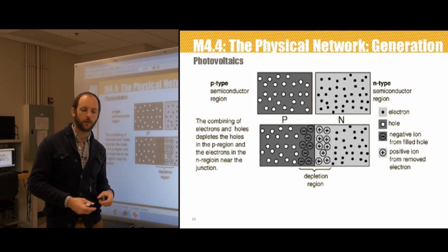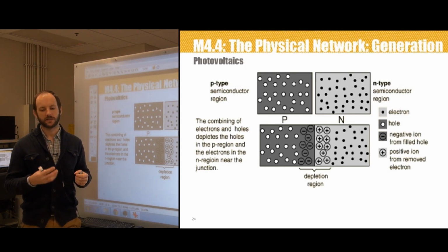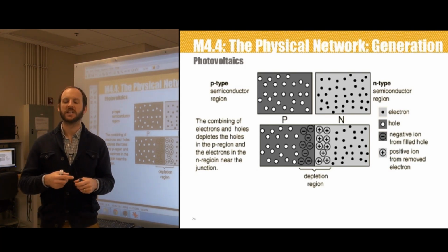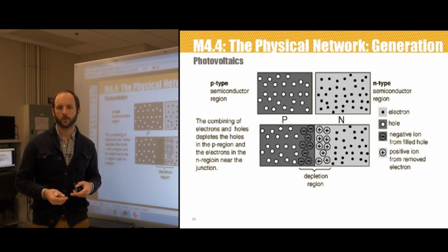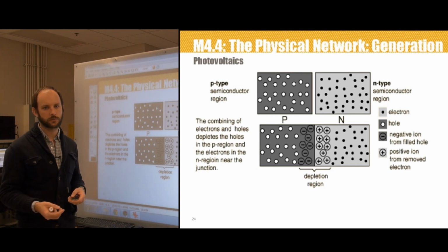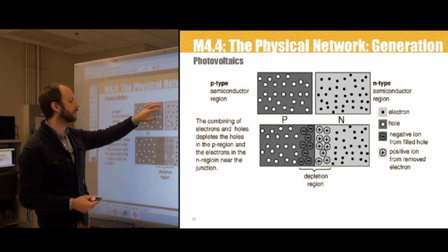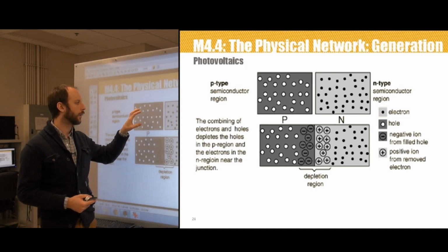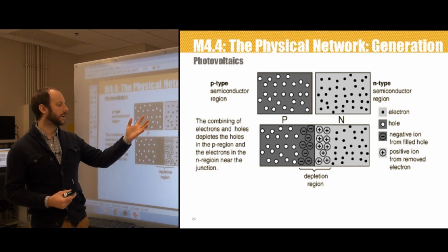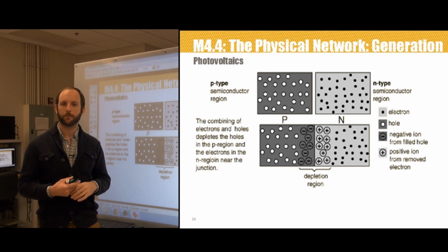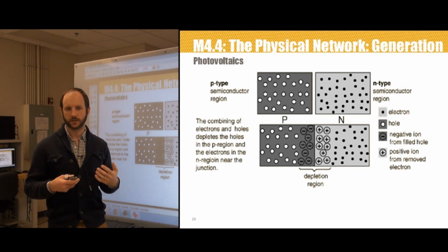that location. Now imagine the same situation, but with multiple empty desks. We can therefore envision that instead of the students moving around, it's the vacancy of a student in a desk that's moving around. And that's what we mean by the concept of holes. It's this vacancy in the crystal structure that's moving around, creating a hole, and because they can move, we have a net hole motion inside of the P-type material. In a P-type material, each hole is considered to have a net positive charge, which is equal in magnitude to the charge of an electron, but it has the opposite sign.